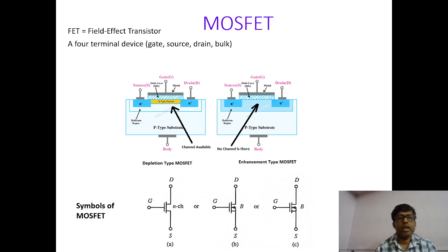This is the metal oxide semiconductor field effect transistor. These MOSFETs have been constructed with various semiconductors such as silicon and gallium arsenide, and with different insulators like SiO2 and Al2O3. The Si-SiO2 combination is the most common. The basic structure of the P-channel MOSFET is shown in the figure, for both the depletion type and the enhancement type.